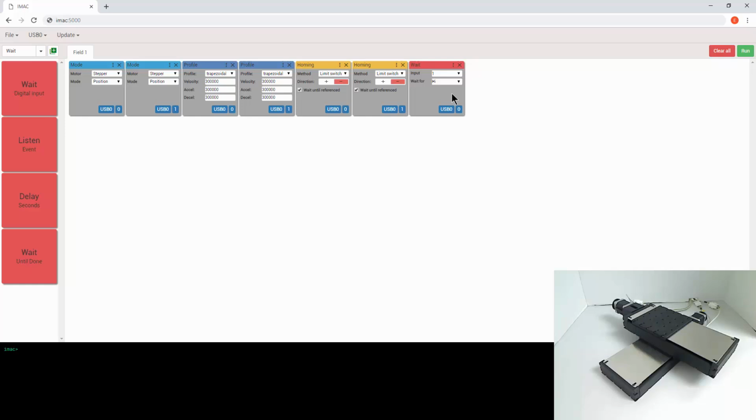For demonstration purposes, I have a two position toggle switch to emulate external input. The switch is wired to digital input 4. When the switch is closed, digital input is low. We are going to wait for the condition on digital input number 4 to be set to low.